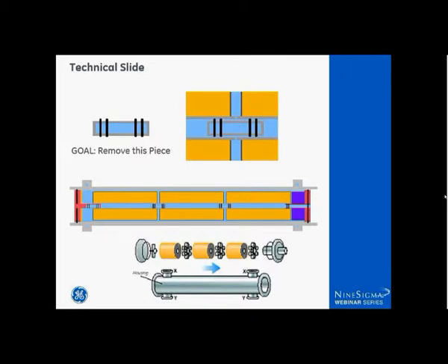And the interconnector fits inside of the central permeate tube, and that inside tolerance is such that when we put 4 O-rings, 2 on each end, the pressure compression on that O-ring is what seals from the outside dirty water to the inside clean water that is flowing inside those tubes.